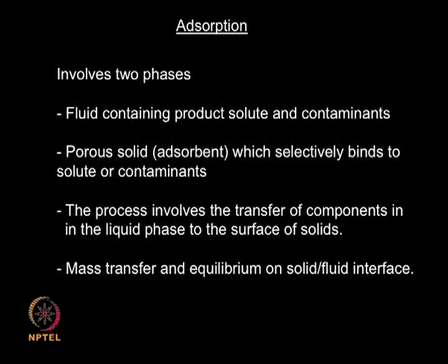Another technique by which we can remove some of the solids present in your slurry which prevent your filtration process is by adsorption. Sometimes, as I said, the filter aid itself does this adsorption process. That means some of the unwanted material can get adsorbed on the filter aid. After all, we are adding a pre-treated or processed clay or cellulosic material or wood chips or carbon and so on. So they have certain surface area which can aid in the adsorption of some unwanted material. So adsorption is another approach by which we can improve the filtration process.